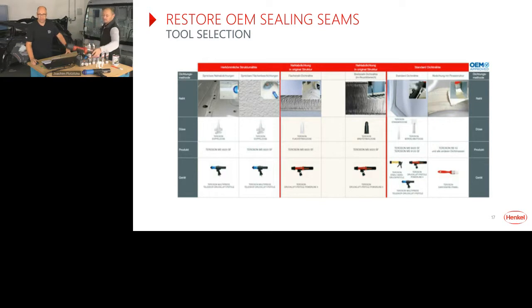And then last but not least, we have for the extrusion beads, we can use standard nozzles like this one. We can cut it into the right shape. Or for the HEMMFLANGE, we will use then this kind of nozzle. The original is like this. So we call it butterfly nozzle because we have two flaps, we have two wings, or wing nozzle, or different words. Okay. So, by the way, this is a very universal nozzle.